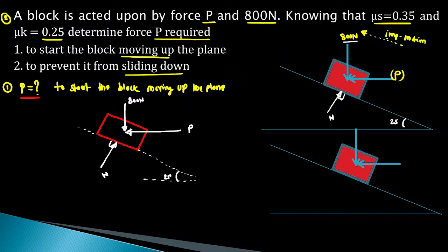And as the impending motion is up the plane, the frictional force will be exactly opposite to the impending motion. So, this is the frictional force which is the F max. Okay. So, right now here we will consider the friction to be the limiting frictional force. So, for this value of P, block will be on the verge of motion. From the calculation we get the value of P as 50 Newton, that is the required value to cause the motion. So, that means for 50 Newton block will be on the verge of motion. Okay. So, that is the equilibrium point.